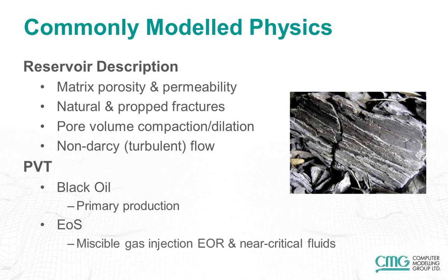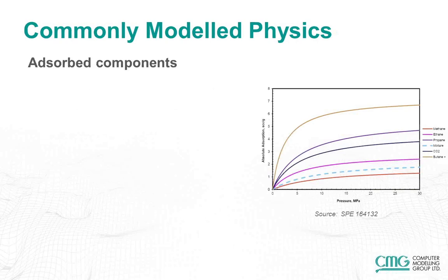So this is especially important if we're doing things such as miscible gas injection EOR, or if we have a gas condensate or a volatile oil fluid in our reservoir. It's much more important to take into account the changes in composition over time. Following this, there's a few commonly modeled physics which may not be included in all simulation cases. So one of these includes adsorbed components and being able to monitor that adsorption over time. This can be used in simple cases where we just want to have adsorption of the gas phase only, such as when we're in dry gas or shale gas reservoirs.